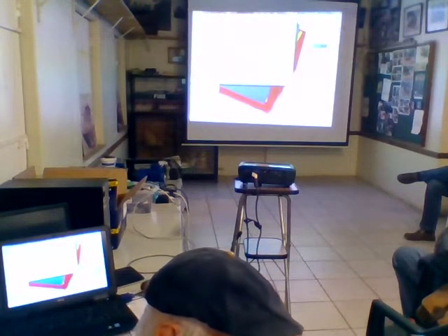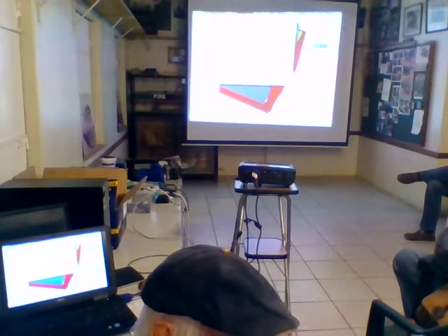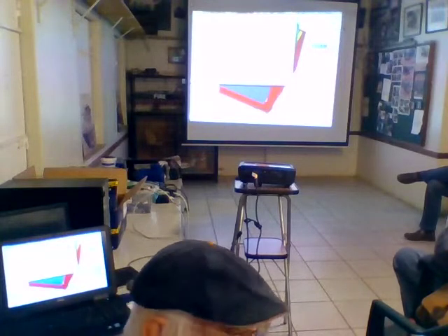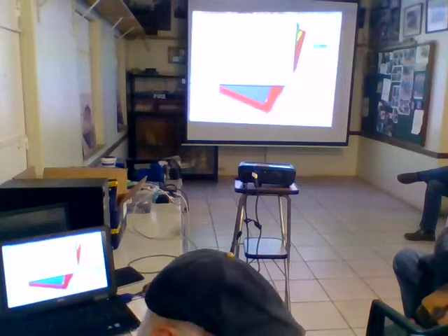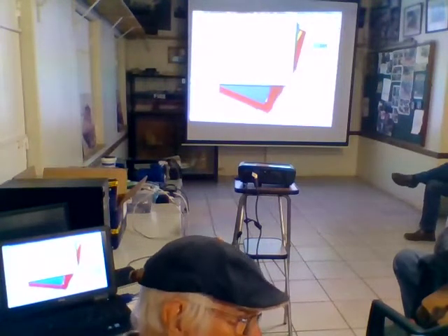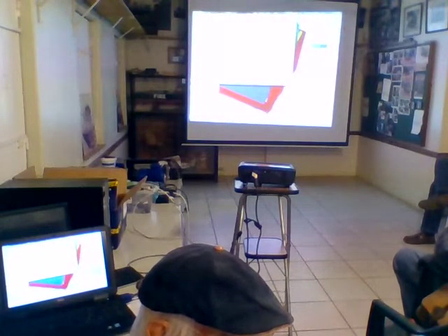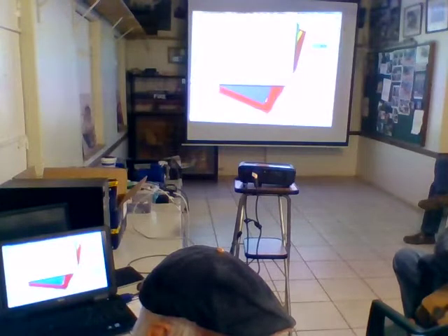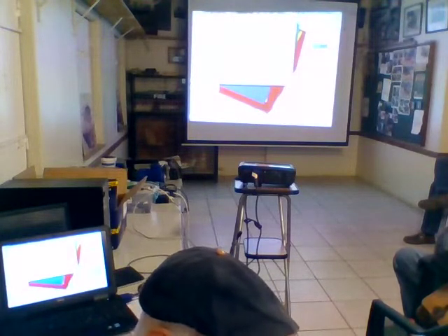We can put in mass, not for stiffness only, but also for mass. Mass influences your frequency. So that's the beauty of this way. If you've got these tools, you can check all of that. You can actually simulate, move the tool, accelerate it, and see what happens. The only other way I thought you could get rid of this chatter is to put a sensor on it, pick up the chatter, and then change your spindle speed. No, we can model it. We can simulate it and model it all in software.